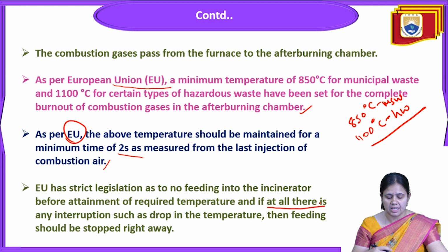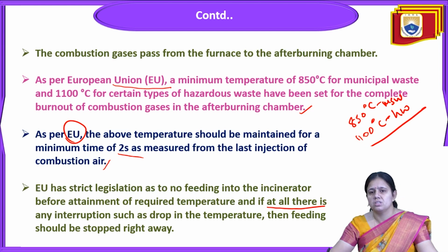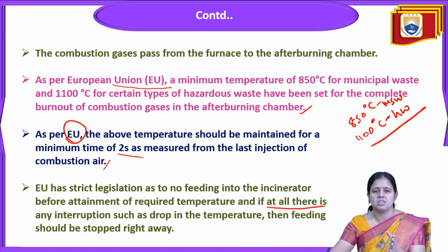If at all there is any interruption, such as a drop in the temperature, then feeding should be stopped right away. So the EU has strict legislation of no feeding into the incinerator before attainment of the required temperature. And if there is any interruption like a drop in temperature, then the waste feeding should be stopped right away, because they have very strict regulations on the feeding of waste and maintaining the temperature. For attaining the temperature for a particular waste, some standards should be followed.